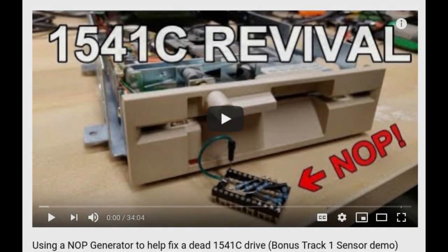In a recent video on the Adrian Digital Basement channel, he demonstrated the use of a NOP generator for the 6502 to troubleshoot an issue on a Commodore 1541 floppy disk drive, and did a very good job explaining how the NOP generator works and how to use it for this particular troubleshooting.